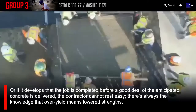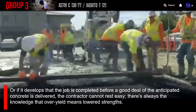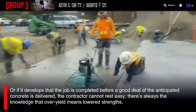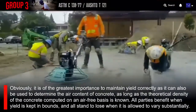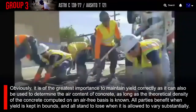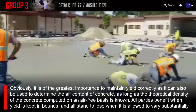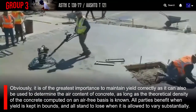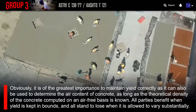Or, if it develops that the job is completed before a good deal of the anticipated concrete is delivered, the contractor cannot rest easy. There's always the knowledge that overyield means lowered strengths. Obviously, it is of the greatest importance to maintain yield correctly, as it can also be used to determine the air content of concrete. As long as the theoretical density of the concrete computed on an air-free basis is known, all parties benefit when yield is kept in bounds, and all stand to lose when it is allowed to vary substantially.